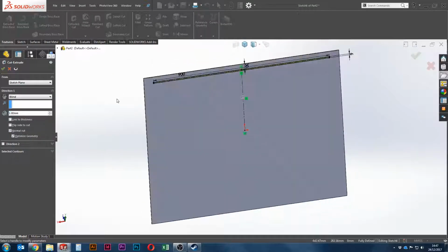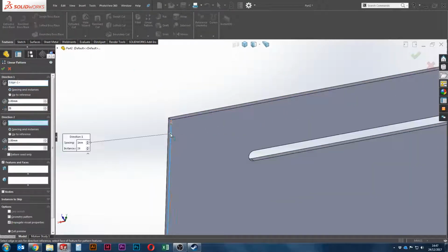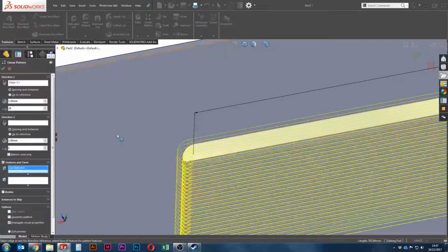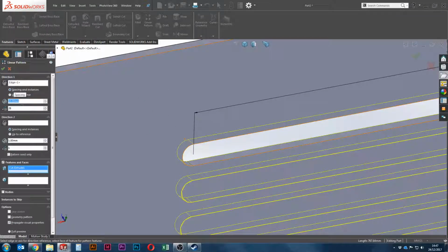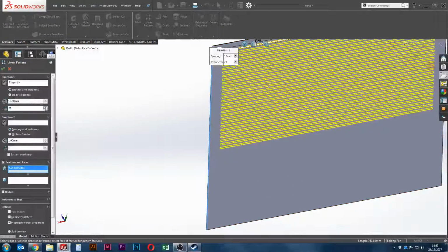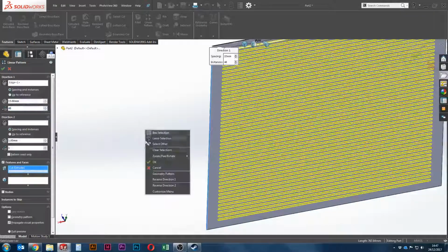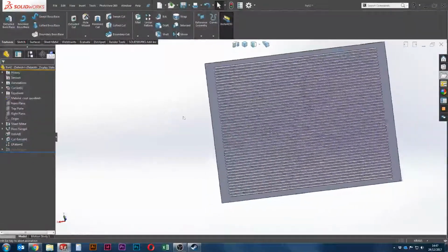And we can extrude cut this, length to thickness, and then we can linear pattern this slot cut down. Features, click on that, and then call it 10mm, or even increase that up to, say, 15mm. Let's see how many times that goes down. It's only rough, this. There we go.